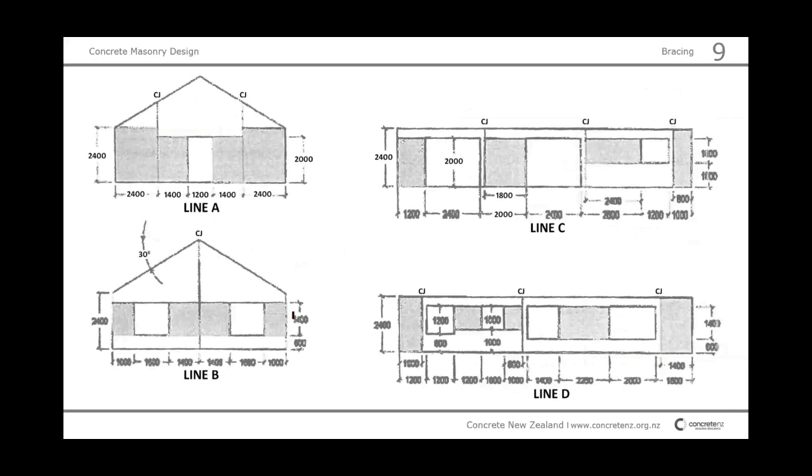Yep. So now we know our building has to provide 3,174 bracing units. We now have to check our 4 panels, what their bracing capacity is. So this one is the first panel I'm going to look at. So we have a construction joint here, construction joint there, and the bracing panel only extends to the construction joints and then to the openings.